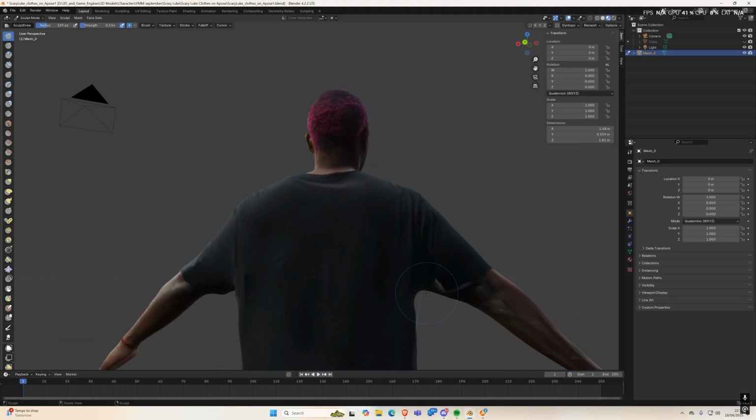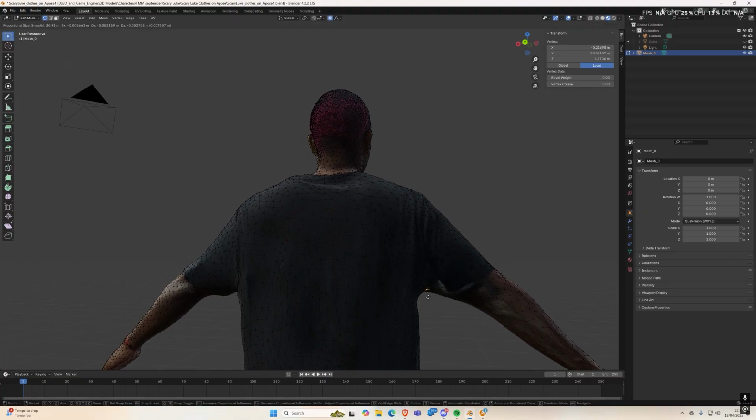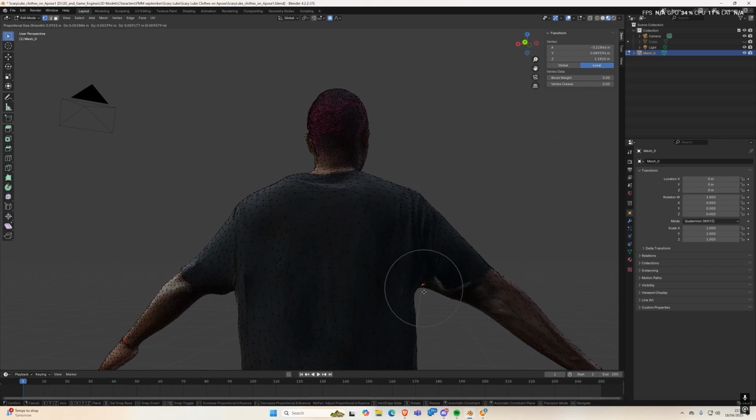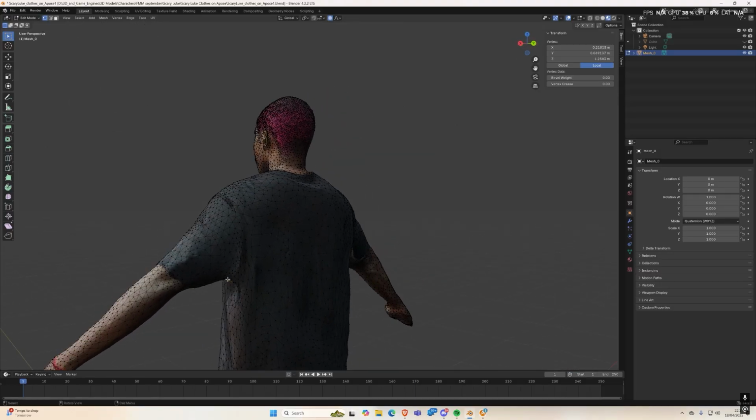Now I'm going to go to edge mode, edit mode, and do a little bit of pulling in. I've got to get the radius of this proportional editing feature down, and just pull all these crevices up. That helps in the animation a bit, because whatever is on the corners there just doesn't animate properly.